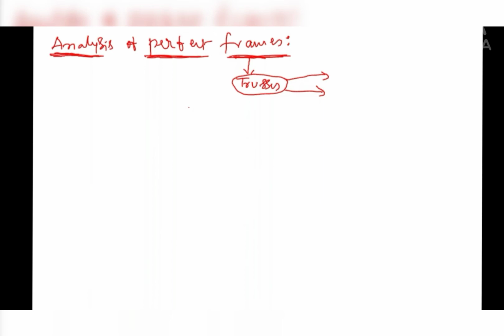So there, the area utilization should be maximum. That means we should reduce the number of columns. So we should put fewer columns there. If we put fewer columns, the load coming onto the remaining columns should be very less. That's why we go for less self-weight members, which will give less load onto the columns which we placed already in the area, right?